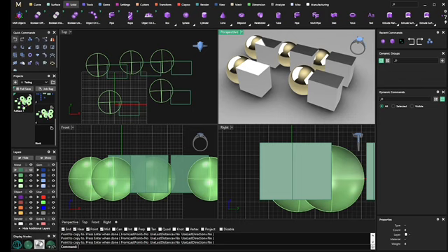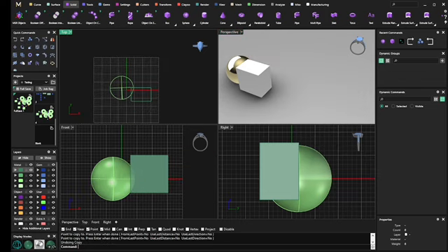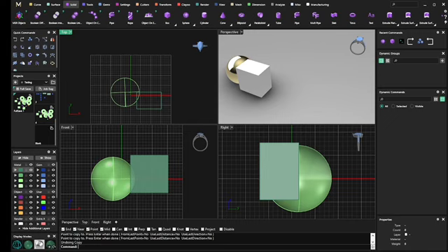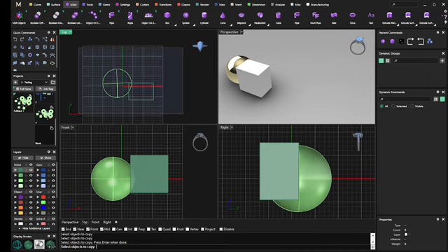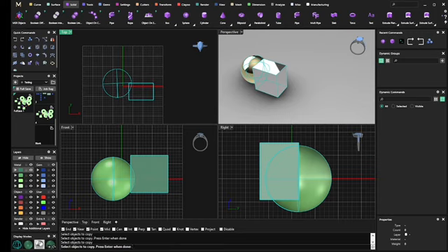Okay, I'm going to undo. Let's say that I am trying to click duplicate, and I don't completely cover the design. Nothing is selected. If I go from the right, I can go part way. Hit escape. If I go from the left, I have to surround the item completely.